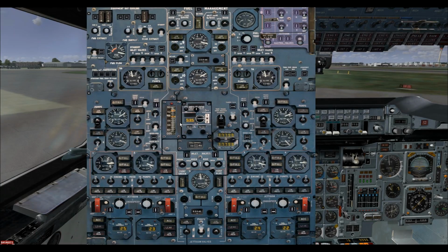All right, so we've let the fuel go back. We're now back to 53.5, so we can turn off our trim transfer and close that up. We can turn our inlets, actually we can leave those shut, and then we just have to reconfigure our load limit controllers back to the original value. This one will go to 0, and this one to 10,500.